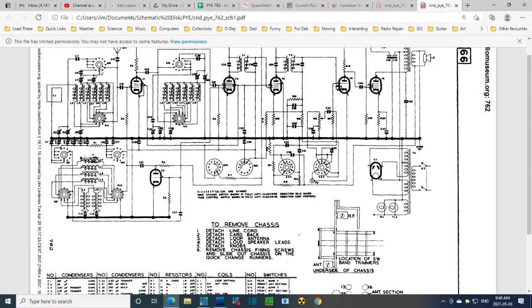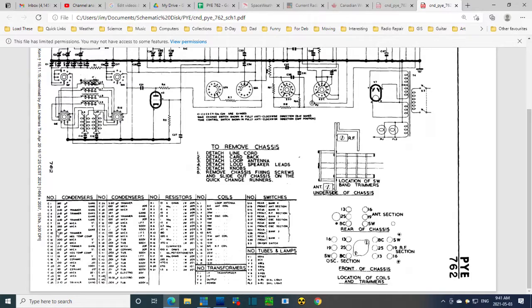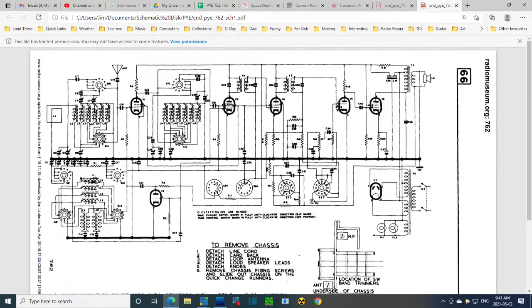So this is broadcast, and it's anti-clockwise, clockwise, so this would be shortwave is here. The band I've been working on, but look, you switch to another. You know, the thing is, this is like a C9 and 14. C9 is the big part of the gang. So when this switches over here, you're actually doing nothing with these. So you are selectively taking different parts of that tuning capacitor and utilizing it, and other parts not being utilized.